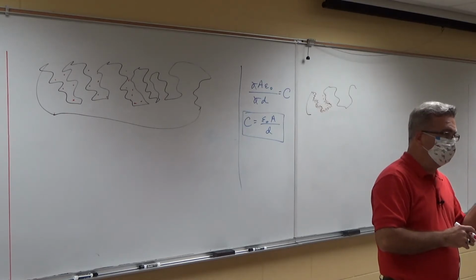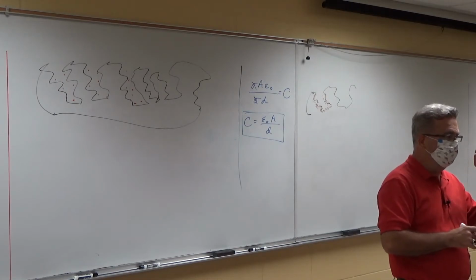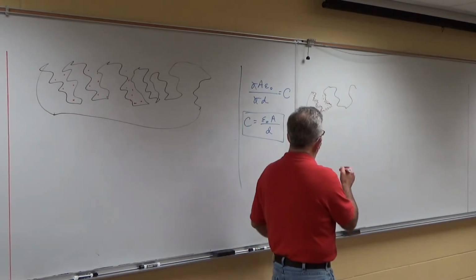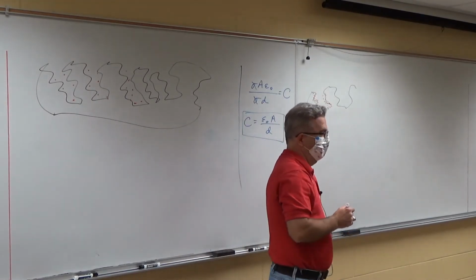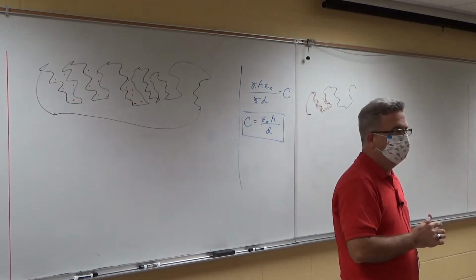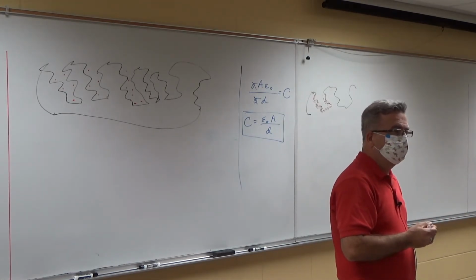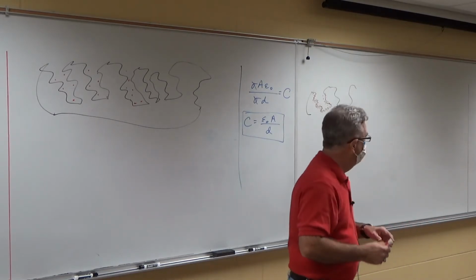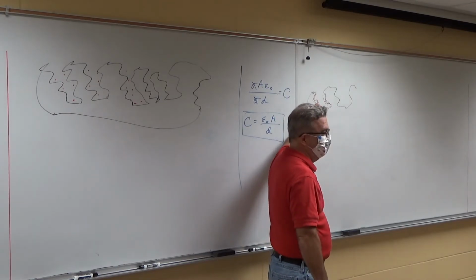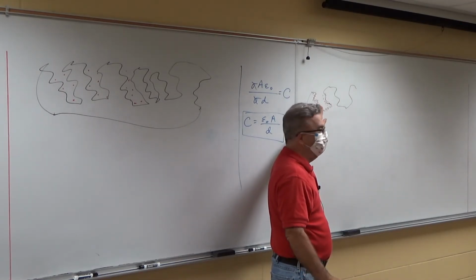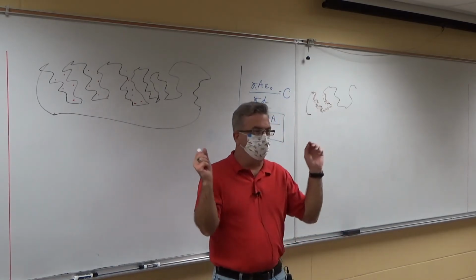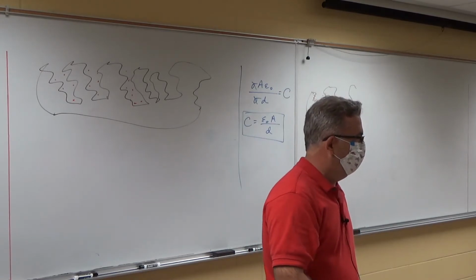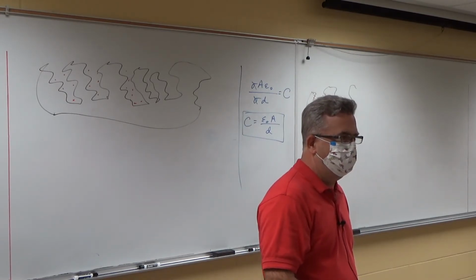If you go over a particular voltage, depending on the way the cap's manufactured, what's going to happen? You're going to get a field that's large enough for the charge to jump the gap, just like a spark. Okay, and that's when the capacitor goes pow. Charge makes it through one little place, and once that dam is broken, all the charge just rushes through, and you get a big spark, and the cap blows up, and smoke comes out, and all that stuff. So you always have a voltage rating on caps.